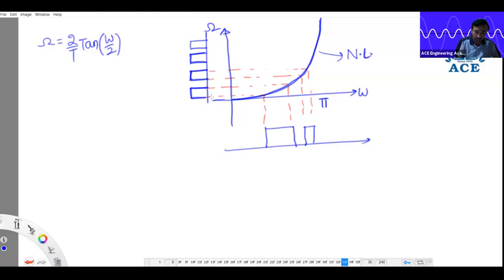And that too, see the cursor, sir, lower frequencies in the analog domain now look like higher frequencies in the digital domain. Lower frequencies in the analog domain now become higher frequencies in the digital domain. They are somewhat squashed up. This is called warping. Warp means bent type of characteristics. So to cancel this effect, we use pre-warping, taking the opposite characteristics, like compounding we use in the communication subject. To cancel that effect, we use the pre-warping procedure. Okay?